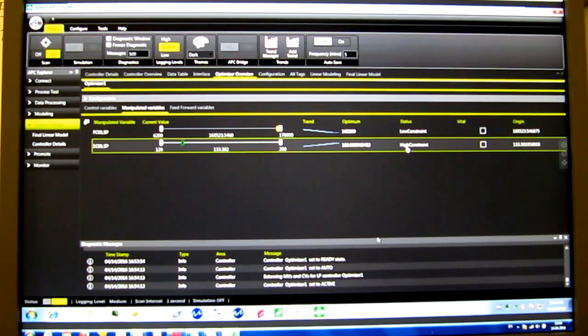And you can see that immediately the system is changing the optimization target, and it's trying to push the system towards another set of constraints, another set of boundaries. But the actual high and low limits that you specified originally are exactly the same. And that's the beauty of this, because you are solving not only the control problem, but the optimization problem, all with the same tool, with two different economic functions running in the same software in parallel. And actually, if the system gets too complex to optimize, you can switch off the optimization function, but keep on running only in control mode.